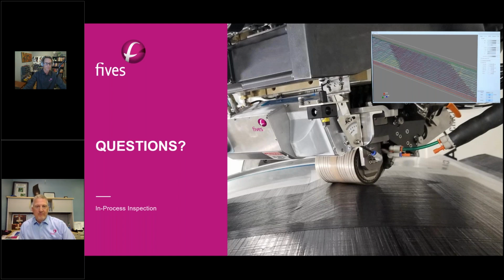Excellent. Can the system detect FOD, or foreign object debris, on the backside of the tow? So you're saying if the tow is on the adhesion side of it. Yeah, we would be able to pick it up if it changed the height of the surface. But if it doesn't change the height of the surface, if it was flat, then it would be difficult to detect. But anything that changes the height of the surface would be identified, even if it's on the back side of the tow.